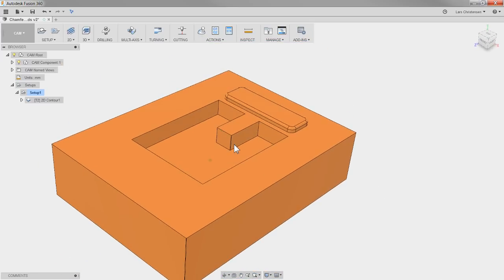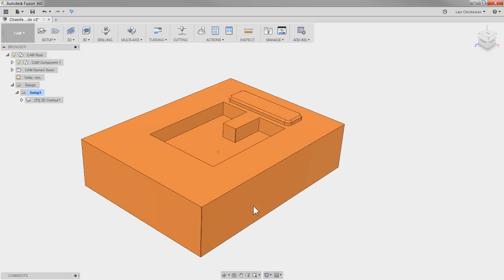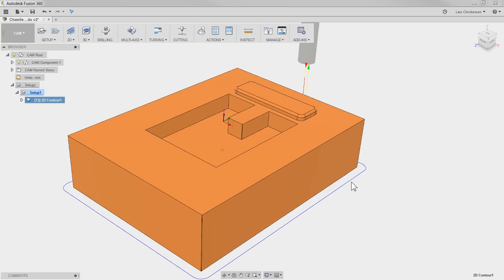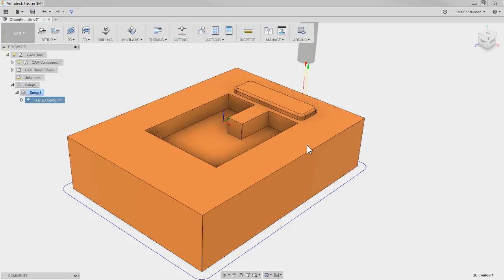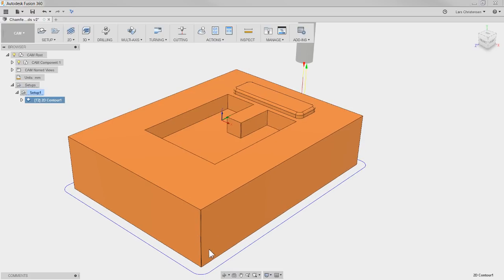And by me adding 30 seconds to a cycle time, in this case just machining around, you maybe have to do that anyways. So you don't even add any cycle time. But even if you're adding a few minutes of cycle time on the CNC machine, you can save an operator like 30 minutes sitting there trying to chamfer things. So that's one little tip I wanted to give you.